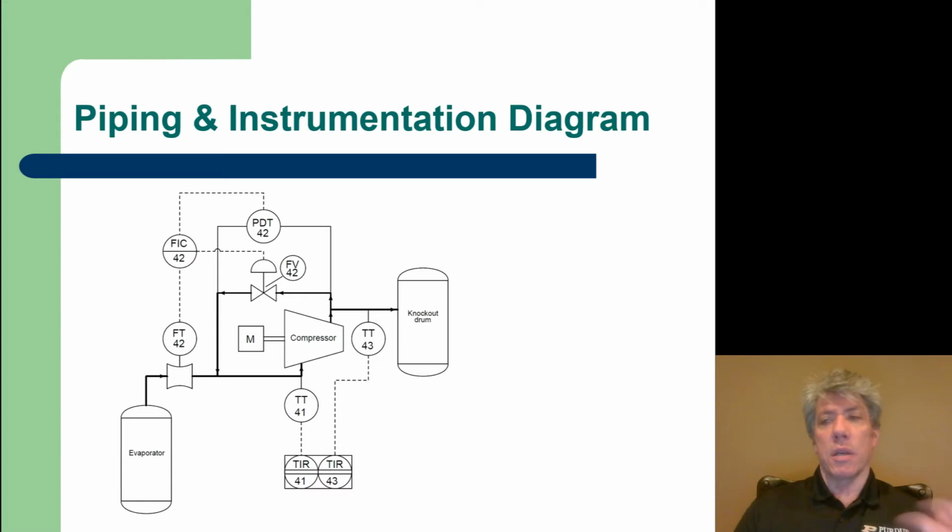Of course, surging indicates the idea that it's surging. There's an increase and then often a decrease in flow, and that change in compressor speed can be damaging. Whatever the reason, we need this flow valve to unload the compressor, so it doesn't destroy itself.